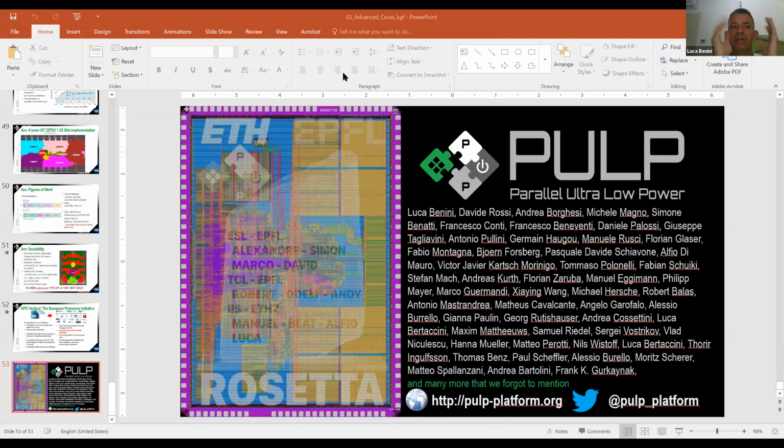There are also other forms of formal verification, such as verifying properties. For example, never deadlock on the memory. And this is also typically based on assertions. So you specify with the logic language something that your design should always do or never do. And then you run the formal verification to verify that these assertions are actually verified.